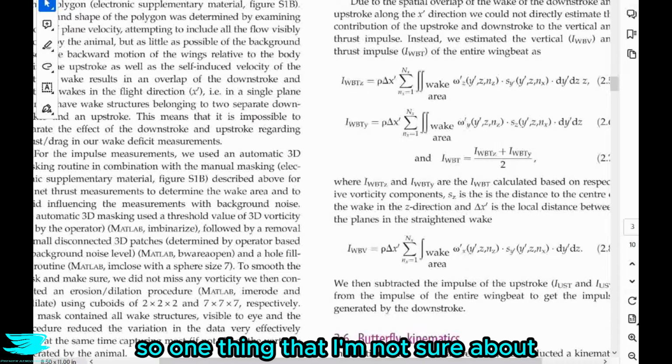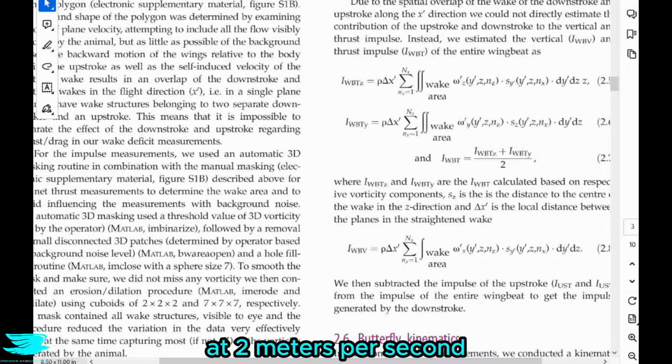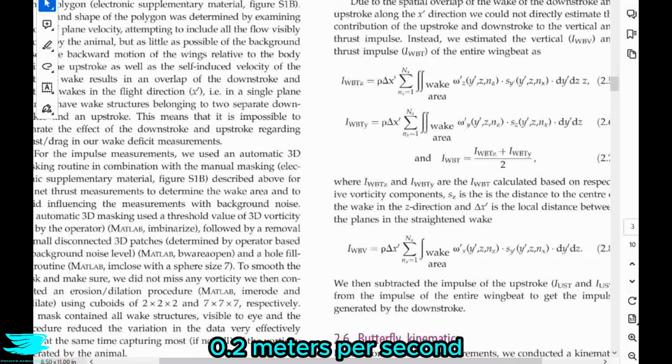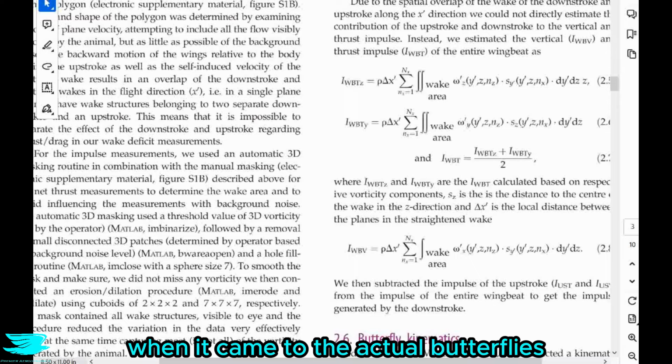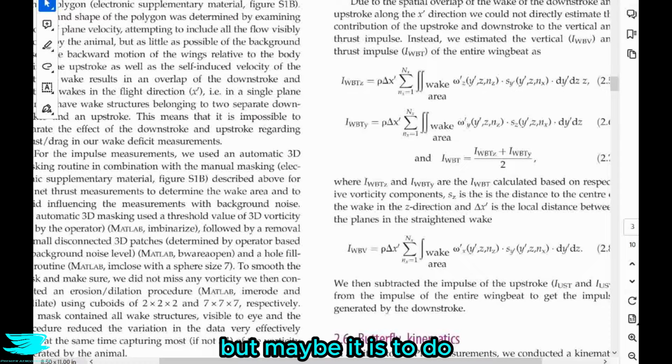So one thing that I'm not sure about in their experiments is that for the actual butterflies, the wind tunnel was run at 2 meters per second, and when it came to their clapper that they made, they ran the wind tunnel at only 0.2 meters per second. They say that they chose this velocity to keep the seeding particles suspended in the air, so I'm not sure why they could run their wind tunnel much faster when it came to the actual butterflies without the seeding particles dropping out of the air, but maybe it is to do with the different PIV setups.